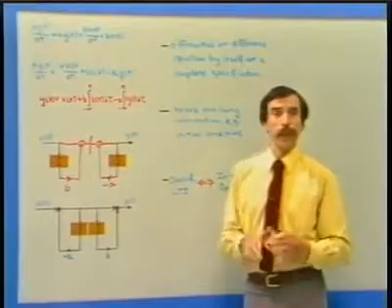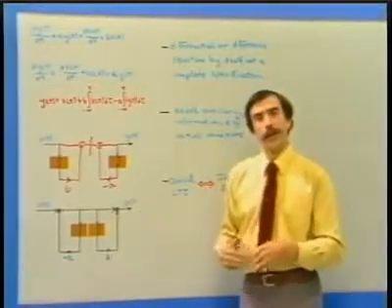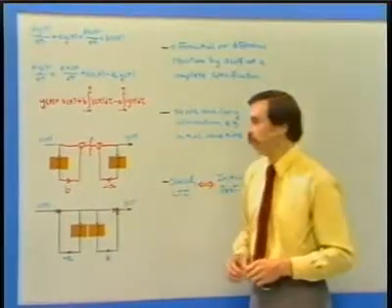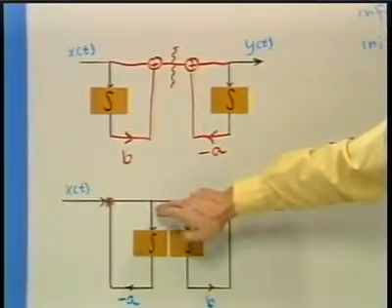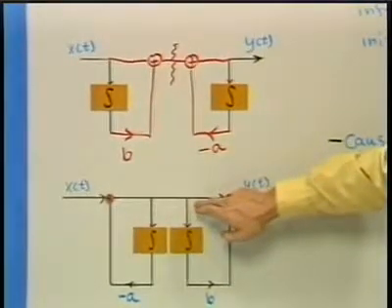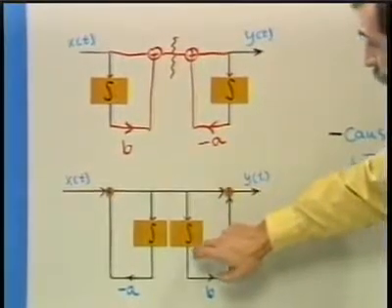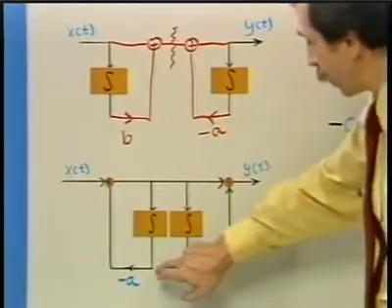And what you can see, just as we saw with the difference equation, is that now both integrators are integrating the same thing. In particular, the input to this integrator and the input to this integrator are identical. So rather than using this one, we can simply tap off from here.